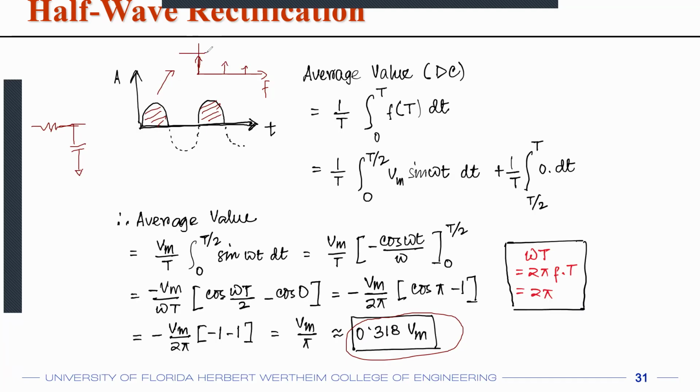Now, if you low-pass filter this, let's say you just take the DC component, then you only have the average. And let's say you cut off all other frequencies present here. So basically the fundamental frequency of the sine wave was, let's say, at this point. If you create a low-pass filter with the cutoff frequency much before the fundamental frequency of the sine wave, then what you are left with is only this DC signal, right?